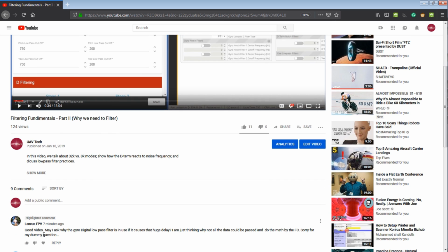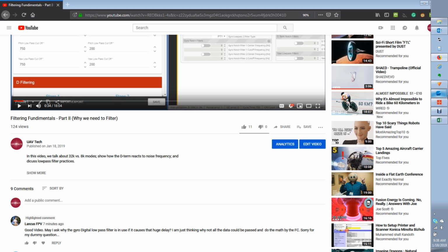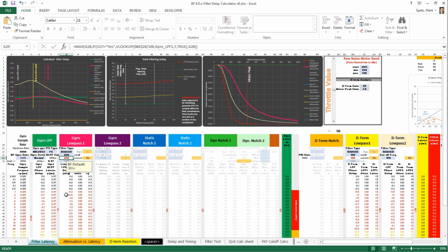There was one really good question on the last one: hey, why do we have this gyro hardware filter if it adds so much delay? And my answer is, is it really that much delay? If you look at it, the hardware filter in the gyro is 0.97 milliseconds of delay. And you could see the data in the part 2 video of how much amplitude and frequency of noise there was in 32K mode versus 8K mode. You can see 8K mode was a lot cleaner coming from the gyro, all for 0.97.